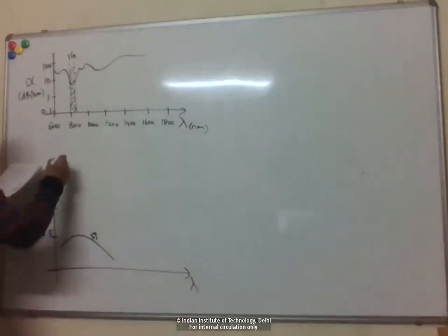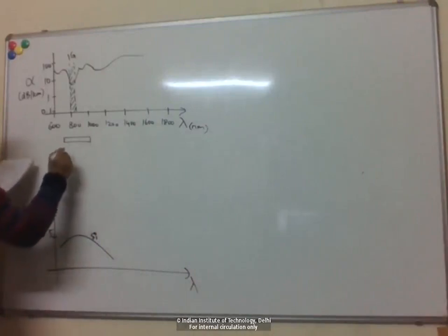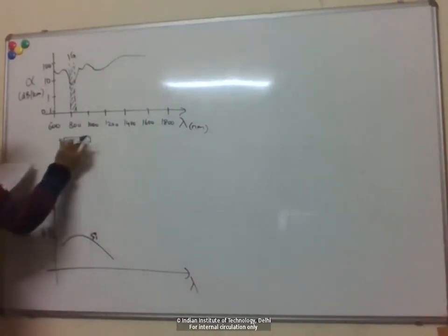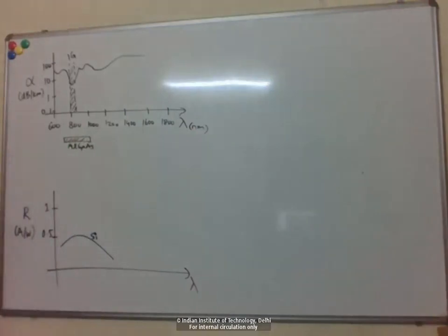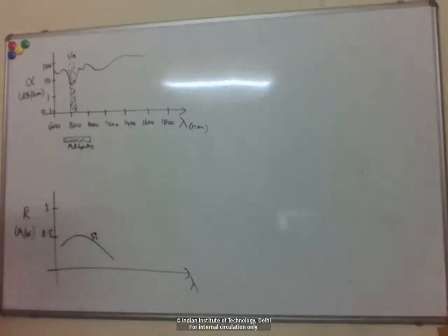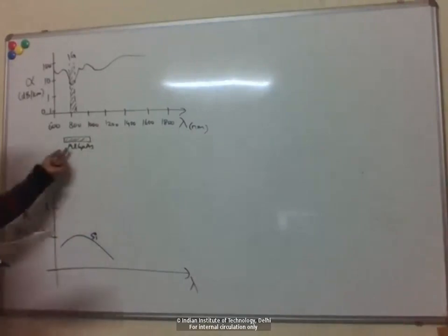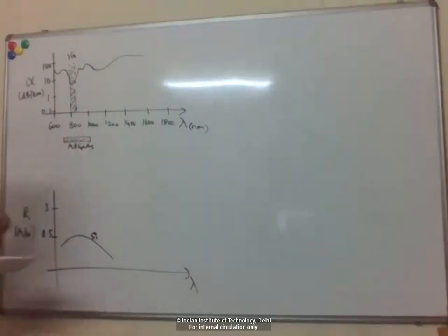So for sources, people developed the AlGaAs technology, aluminum gallium arsenide, again based on III-V semiconductors, which had this range of wavelengths. Aluminum and gallium are group 3, arsenic is group 5, and depending on the different mole fractions of these atoms, one could tune the wavelength in this range.